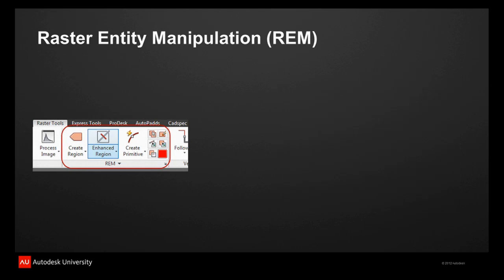Now, this brings us to raster entity manipulation. Raster entity manipulation is basically something that creates AutoCAD primitives by retracing the original pixels in a defined area. And then we can manipulate those entities. I'll refer to raster entity manipulation as REM. Not the band. But anyway, you can use that as standard lines with grip points where you can reposition those start and end points, and it will then recreate the raster data according to those entities.